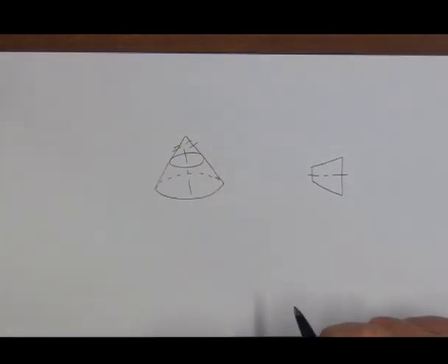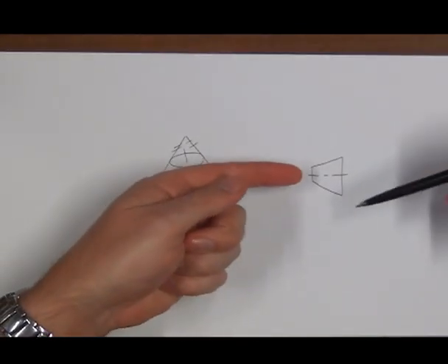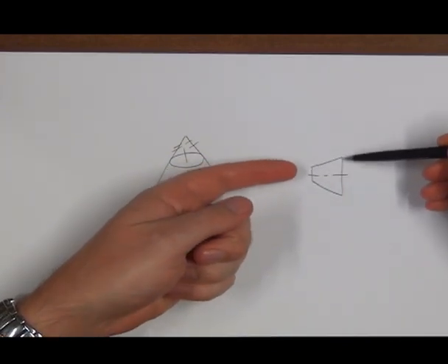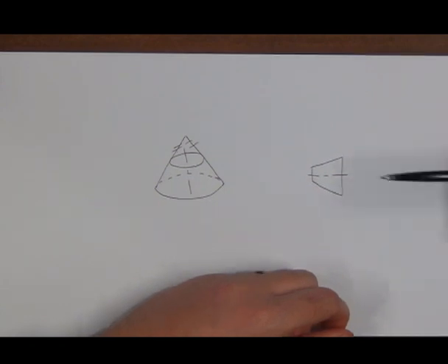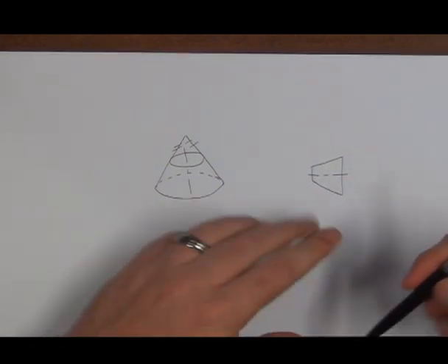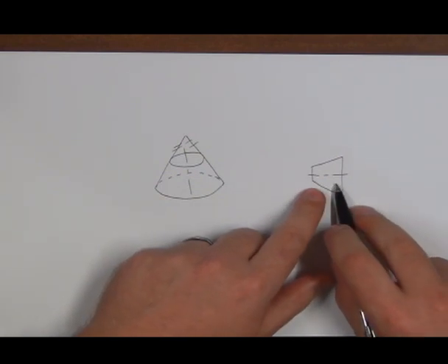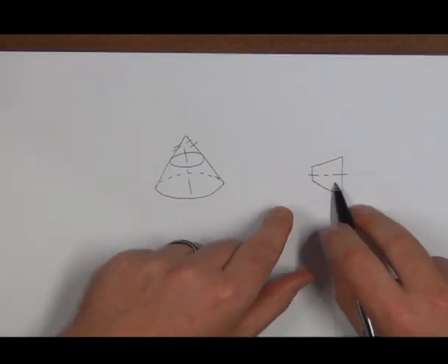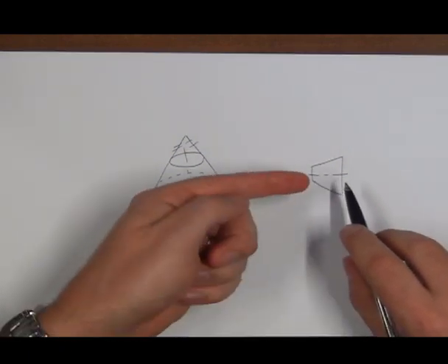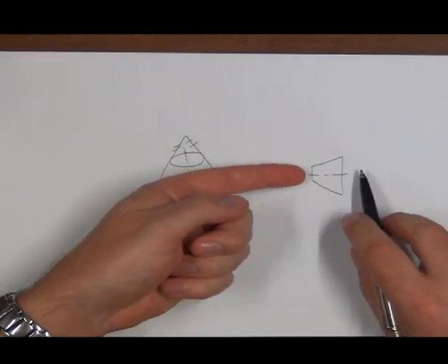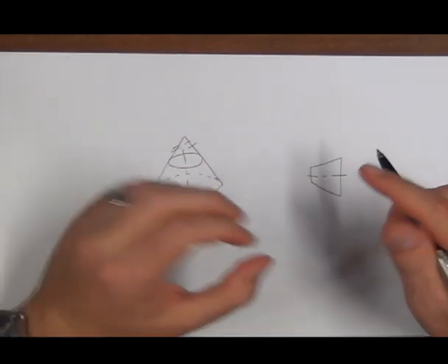That's the one view. And the other view, if I view it from the left hand side, I will see a small circle and a big circle. If I view it from the right hand side, I'll only see a big circle. So the idea of the projection symbol is we take this cone and we then show the reader of the drawing where they can expect different views. For example, a left hand view of this would produce a small circle inside of a bigger circle.